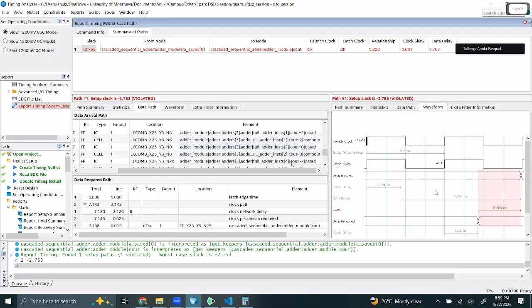If you want to confirm the actual path the signal is going through, we can do that. In Vivado, there is a nicer interface that shows a visualization of the different blocks and highlights the path between them, but I couldn't find that in Quartus.